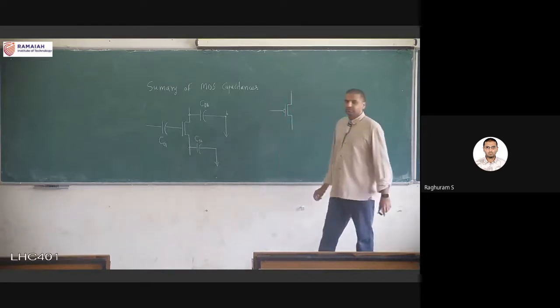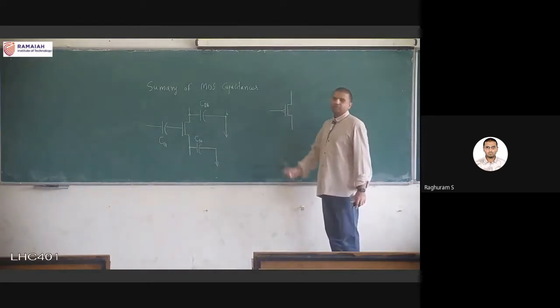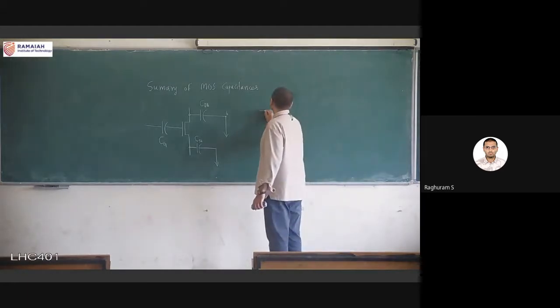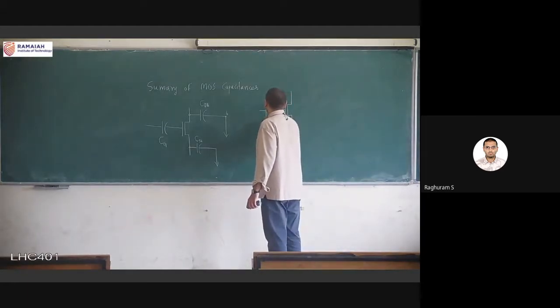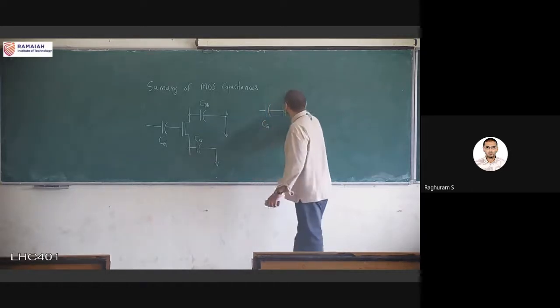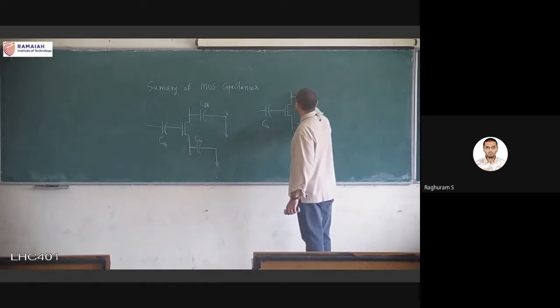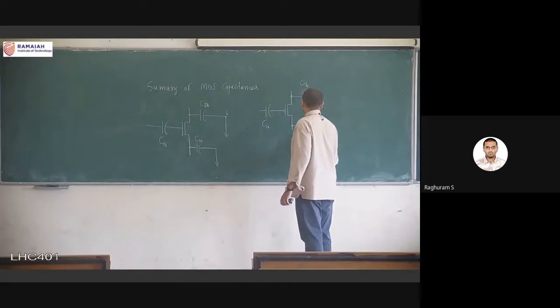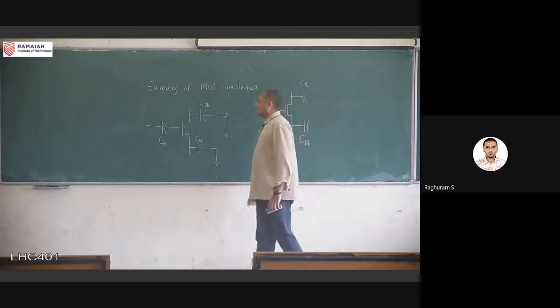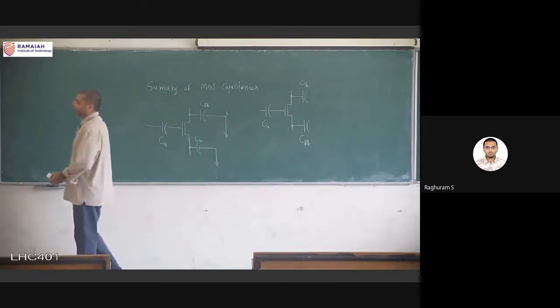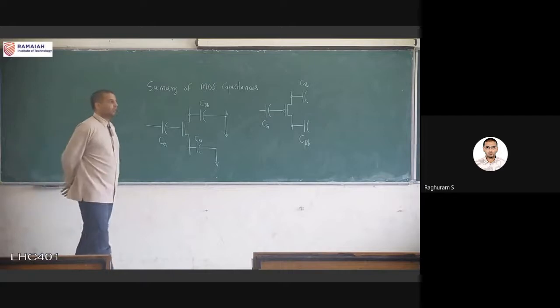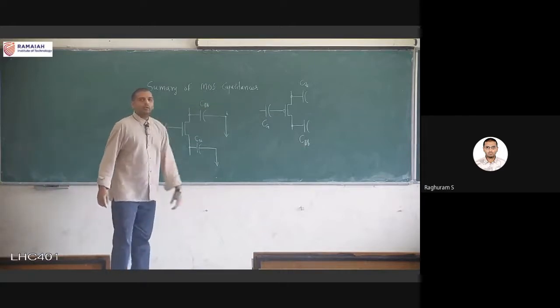Okay, PMOS transistor, everything is same except we have the bubble. So the first capacitance is identical, CG. Okay, and the second and third are also almost identical. Now one question I want to ask is, for PMOS transistor, the diffusion capacitances, which I have half drawn there, how do I complete that diagram?